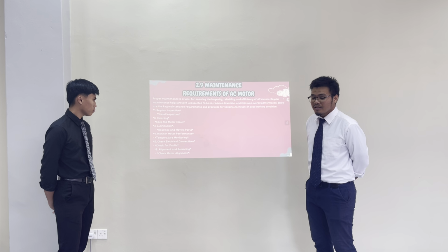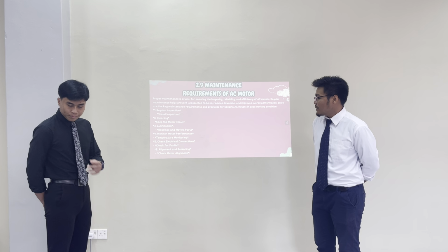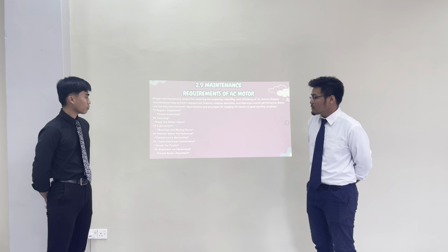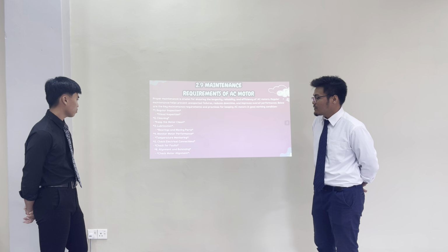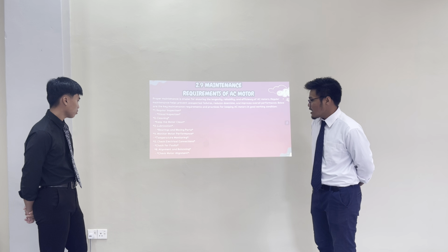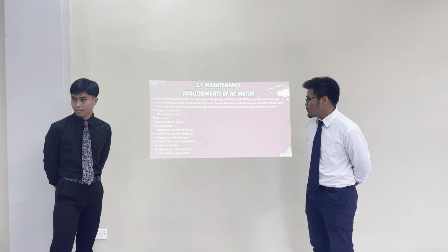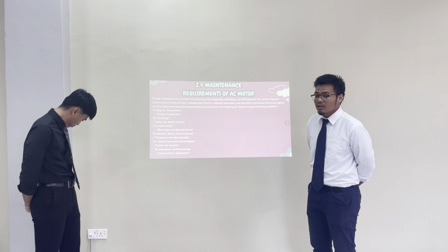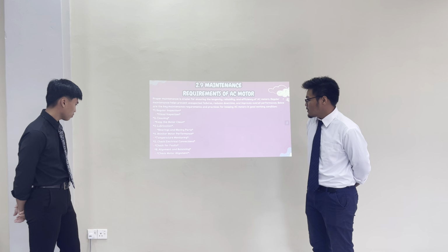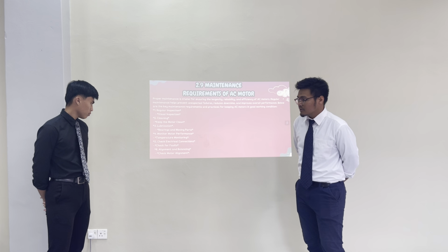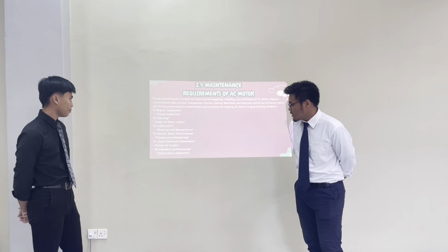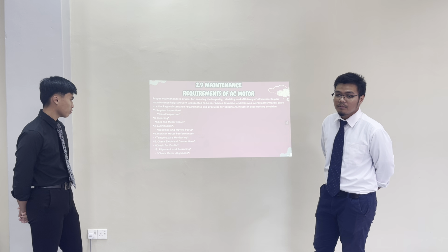First, regular inspection, visual inspection. Number 2, cleaning, keep the motor clean. Number 3, lubrication of bearings and moving parts. Number 4, monitor the motor performance, temperature monitoring. Number 5, check electrical connections, check for faults. Number 6, alignment and balancing, check for motor alignment.